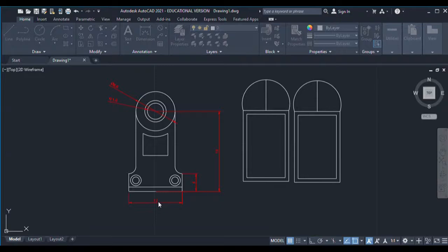You click DWG to PDF, and then here you can click the size that you want. I will leave the ISO A4 format, just like that. Okay, you can see that my drawing is being picked here. I'll also say, okay, I want this thing to be the center, and I want it in a landscape.